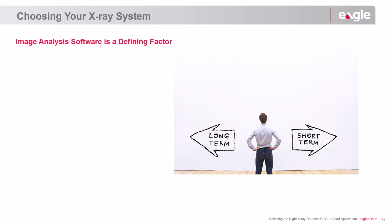When choosing the right machine configuration and detector types for your X-ray systems, several key factors must be considered. There are various detector sizes available, such as 0.4 mm, 0.8, 1.2, etc., but selecting the one with the smallest number isn't always the best choice. Instead, focus on the detector that best meets the objectives of your food safety program. Evaluate your production line, application specifications like speed and contaminant detection needs, production environment, and budget to determine the optimal